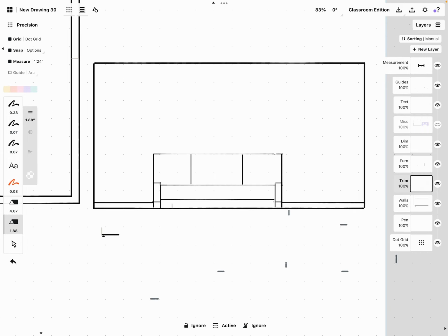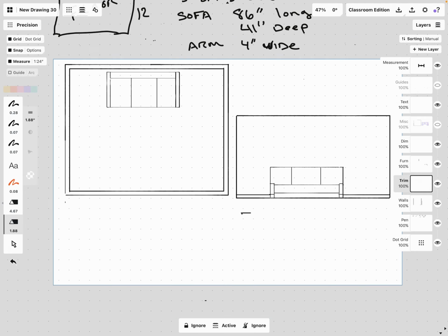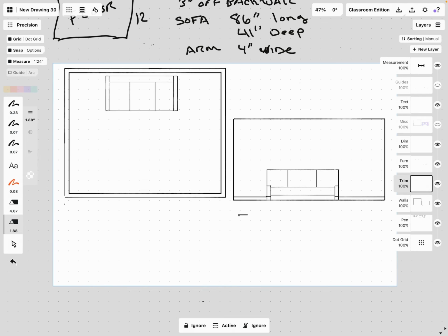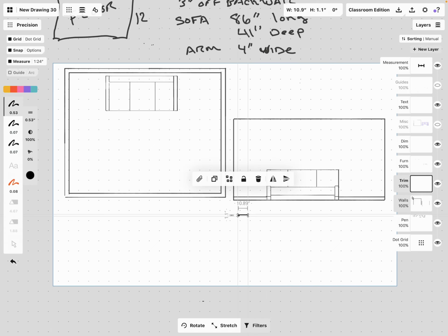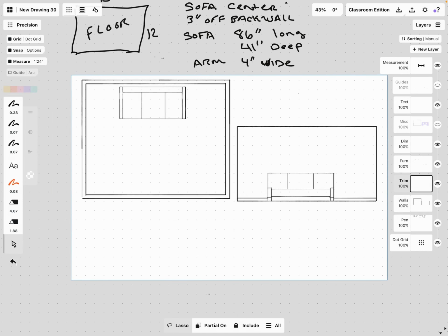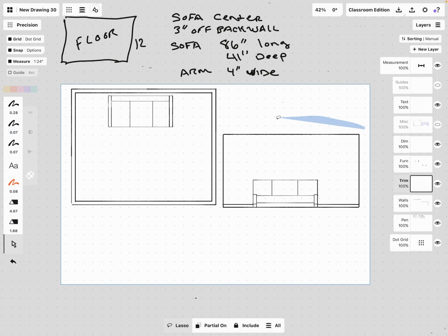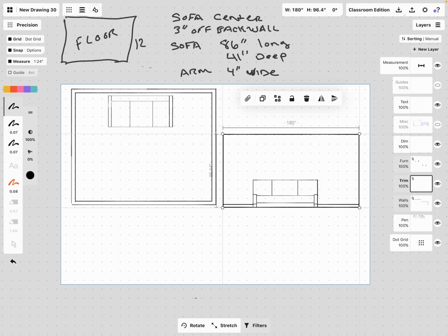When you're adding your dimensions, we're going to do the same for our dimensions. Click on the dimension layer or create that layer. Draft your dimensions out just like we know how to draft. We know our dimensions do not touch exactly to our corners. We're going interiorly.